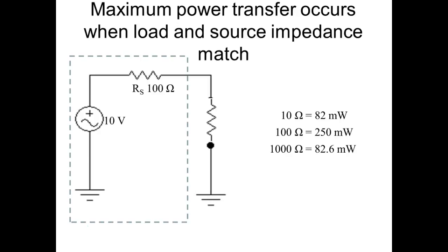It's just that we don't include the impedance of the wire because we basically just use duplex, twinplex, or whatever wire. But you have to match your speaker to the output impedance of your amplifier. The output impedance of your amplifier on car stereos is like 2 ohms. House stereos is 8 ohms. So you don't want to hook up speakers in parallel, because as soon as you do, you get distortion. Why?